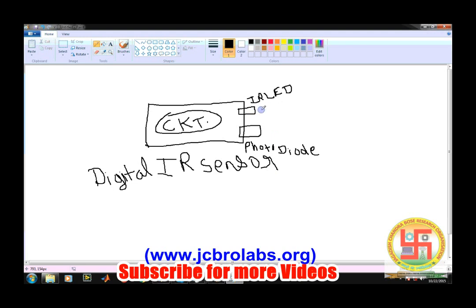The IR LED is emitting light in the forward direction. If this photodiode is not receiving anything, the output will be 0. As soon as there is some obstacle, some of the light will come back to this IR sensor, and since we have set the reference point within the circuit as discussed previously, the output will become 1. So are you getting how the IR sensor is working?